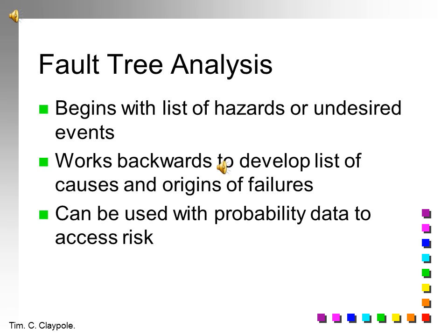The failure is caused by an incorrect location in the drill fixture. Currently it relies on operator inspection. So the risk of it occurring is 5, the severity is 7, and the risk of it not being detected is 6. This gives us a risk priority of 210. So it's quite a risky part of the production process.